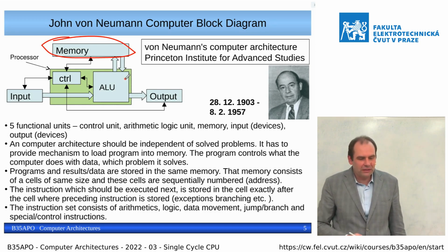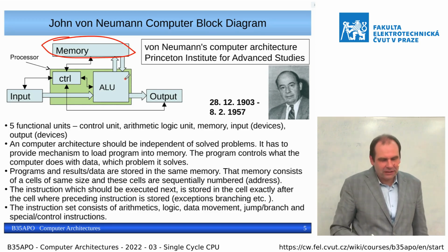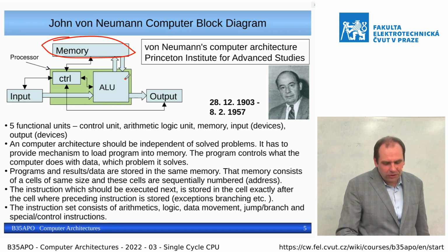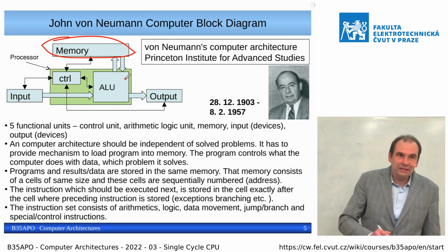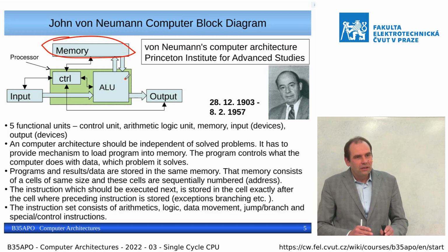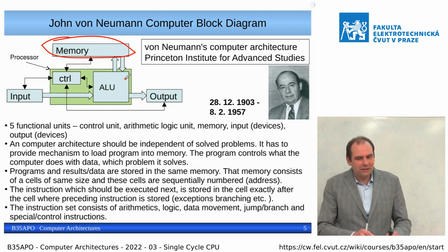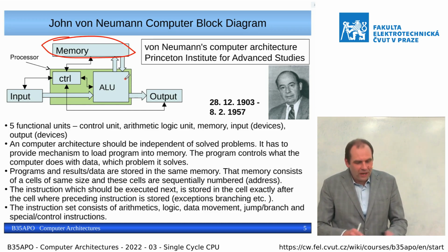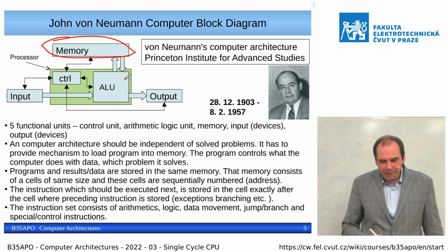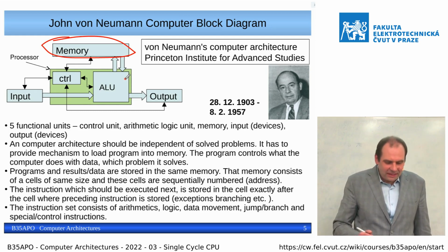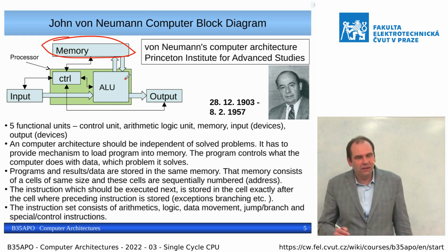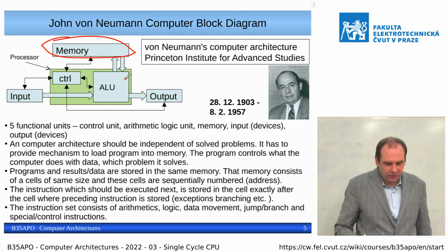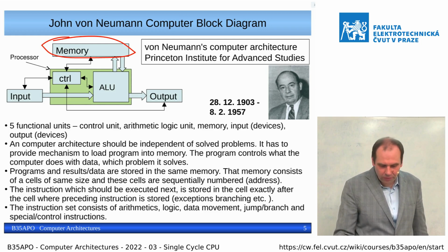It is a big difference when we compare it with the Harvard architecture, which has separate buses for instructions and for data. It has the advantage that we do not need such a big bandwidth, basically the instructions do not collide with the access to the data memory, but it has the disadvantage that we cannot load and run a new program without some external tool on Harvard architecture CPUs. So it is important. Von Neumann allows this.